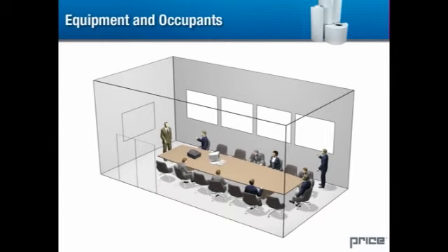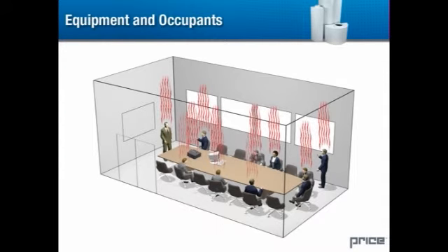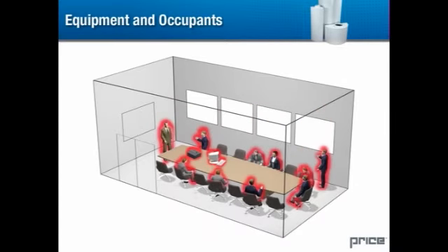We know that task lighting, equipment, and occupants located in the occupied zone have thermal plumes. These naturally exhaust a portion of their heat to the upper zone, even without cool supply air. As a result, a portion of their convective load is passed to the upper zone, while some of it remains in the occupied zone. These surfaces also radiate heat to other surfaces, but for the same reasons as with the solar load, some of this may be outside of the occupied zone.